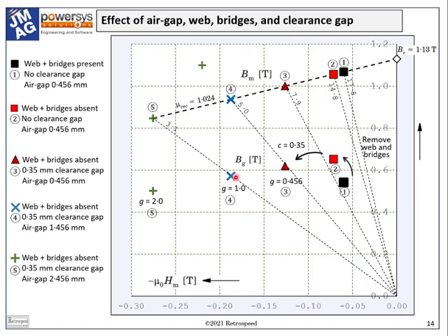What is the trade-off between increased flux on the one hand and the cost and manufacturing difficulties associated with this unusual method of construction? Note that the magnet operating point in case 4 is 0.938 Tesla with a permeance coefficient of 5, which I would say is starting to approach the lower range of recommended values for open circuit operation.